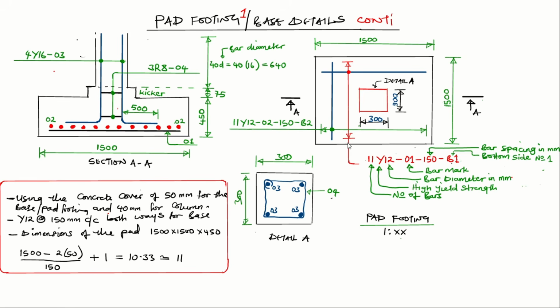Then this whole thing here, the one in red, shows that this reinforcement is being distributed along this axis here, which is the horizontal axis. So it's being distributed along the horizontal axis at the specified spacing. For example here, the spacing that we're going to be dealing with will be 150. So you're showing that this reinforcement is being distributed at a spacing of 150. In which direction? The horizontal direction, coming down here. This is what this means, and you must always show it in your sketching.